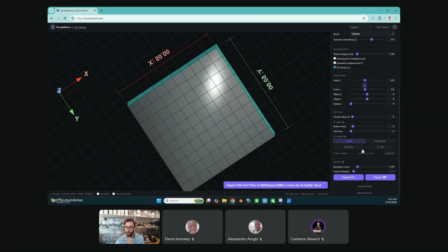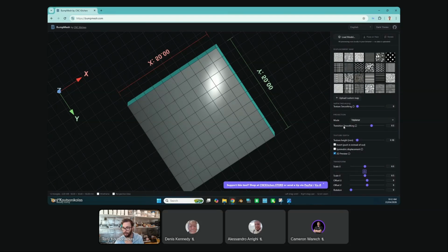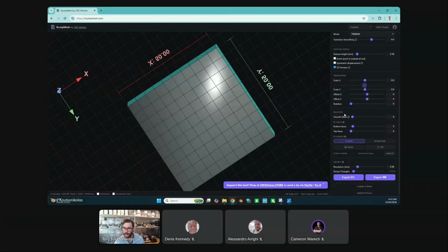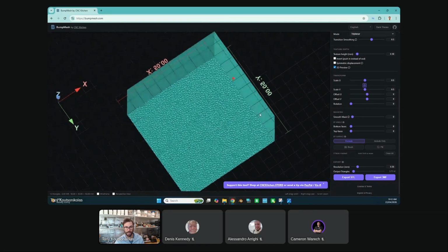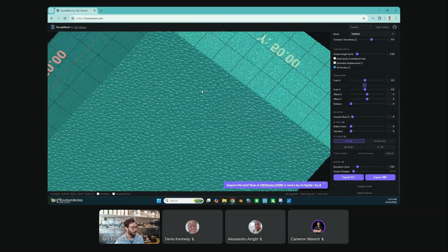So he's basically excluded the bottom with, where is it? It's called texture masking. Yep, so see here under masking, not mapping, we've got bottom faces. So if I turn that to 0, the bottom face has now got the texture applied. So depending on your model, the orientation that it comes in, you might want to turn this on or off, right? But if I go and 3D print this now, and I've got a texture on the bottom face, that's not really going to work, okay?